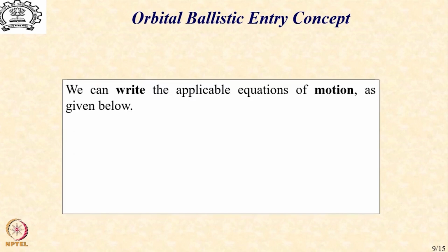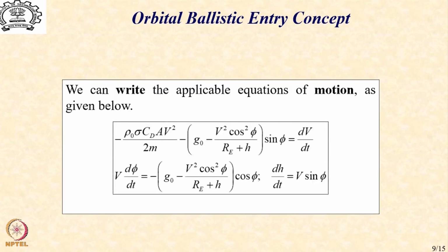So, in this case, the model equations are that apart from the drag term, which is the same as the steep ballistic trajectory, we include both the gravitational force g0 and the centrifugal force term, which is significant due to large velocities, and then of course it's a two-dimensional motion instead of the motion being along a straight line.